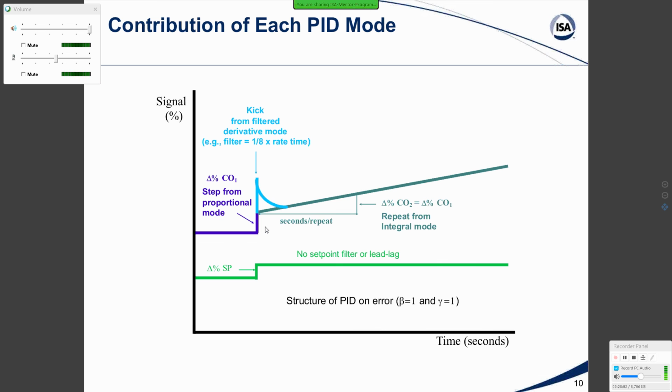Unfortunately, it was a level loop on the column, and for that type of application, for controlling reflux to the column, it made the column work that much better, and they thought it was all due to the migration project, when really it was just due to a misunderstanding between proportional band and controller gain.